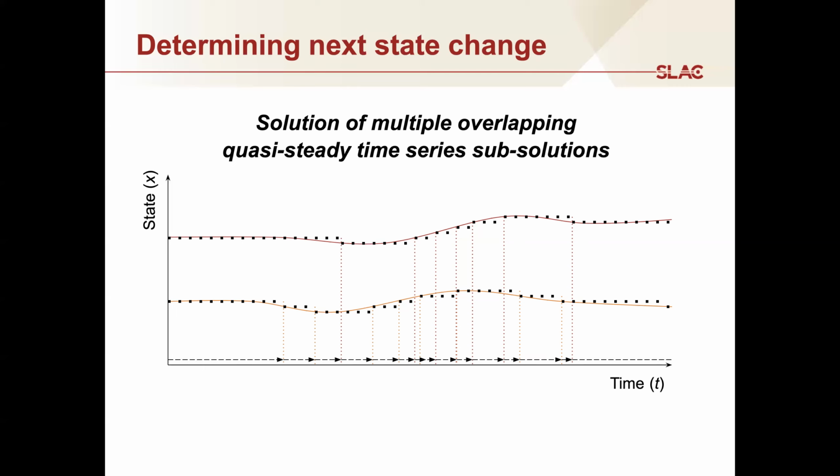And oftentimes, as we make the object models more detailed, the solution tends to approach essentially a finite difference solution, and the overhead of doing all of that work is not worth it, and you might as well just switch to a finite difference solution, such as what we do with dynamic transients, where we know that essentially every time step, everything is affected, and it's not worth going through all the trouble of asking, and we simply switch to differential algebraic equations instead of ordinary differential equations.